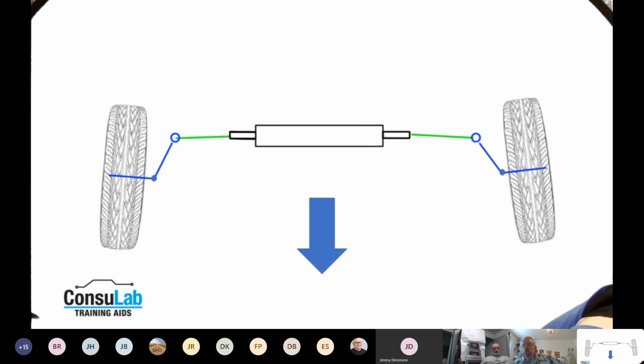So again, with the Ackermann angle or toe out on turns, lots of things can affect this. There have been, again, playing around with things where people take an old car, like the one I showed you yesterday, and try and put rack and pinion steering on it. So they'll mount a rack off something else and connect it to the stock steering arms, and end up with all kinds of problems because you've changed so much of the steering geometry that it changes the turning radius of the car. You've got to change steering arms. So it's not just a matter of doing those swaps.